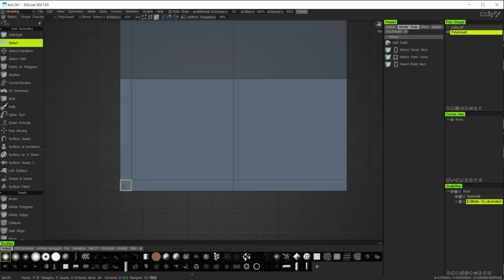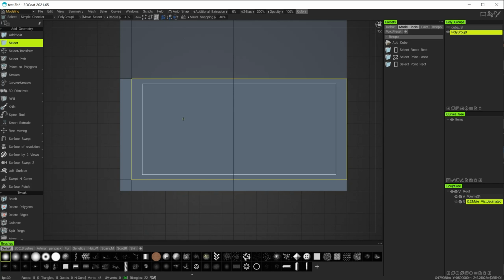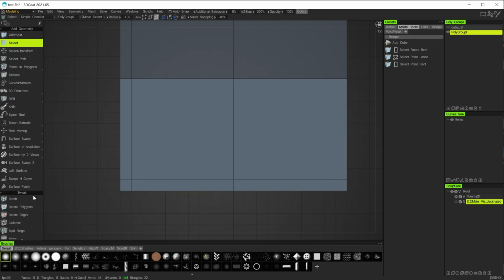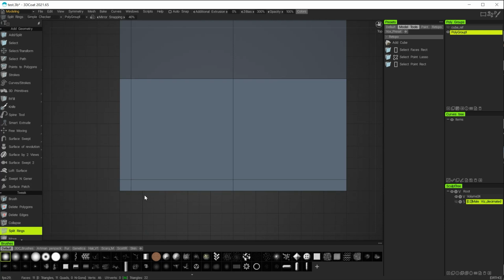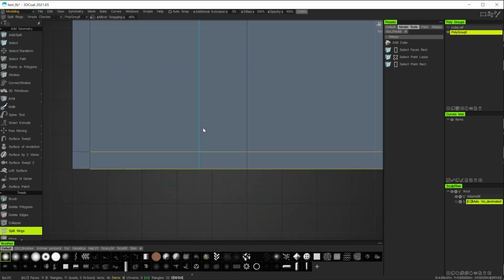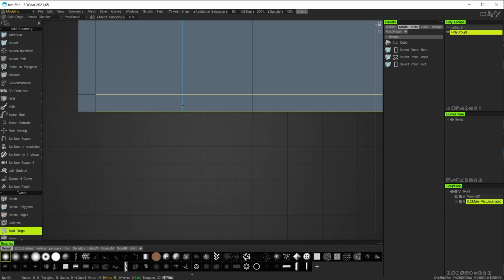And from the platform here that I've created, this 1/2 meter gap platform around the building, I want to go roughly 2.5 units in and place the end of my wall there. Again, I'll use the split rings tool for this, and I'll make sure my measurements are correct and I'm roughly in the right place, which is roughly here.